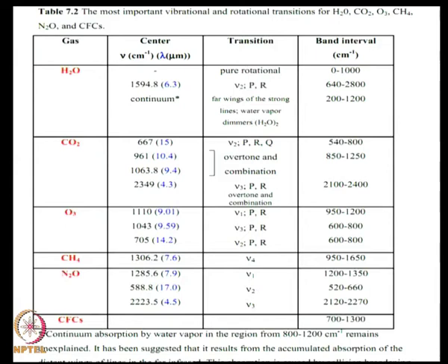And so, this is a point we have to remember, that in any given wavelength range more than one gas can be absorbing irradiation. So, you have to correctly account for overlap of the absorption bands of different gases carefully, because in most situations we encounter the gases which are absorbing are many, and hence their role must be fully recognized.